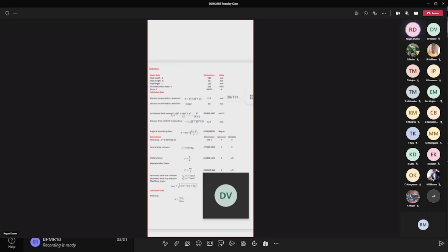You guys understand what the difference between I and J is? I being the second moment of area and J being the polar moment of area. Does anyone know the difference? Okay, so I is a resistance to deflection in a translational mode, where J is the resistance to deflection in rotation. When we try to rotate something, we try to twist it.